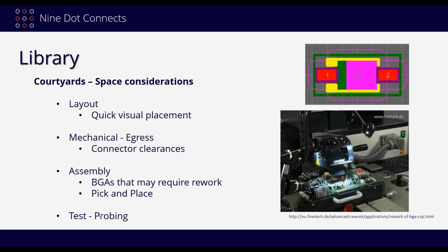And then lastly, the idea of probing for tests. So if there's enough space between these things, you can do things with it. For example, you can get a probe on top of it, not worry about it sliding off. Or sometimes if you've got to do things like dead bugs or tombstoning in order to do a bypass, then with this courtyard over here, you can allow for human manipulation.